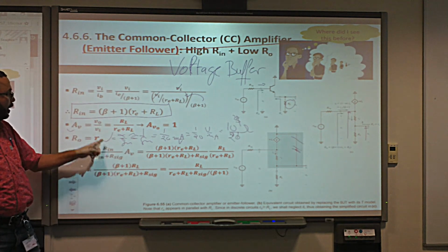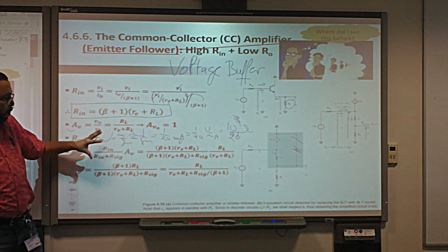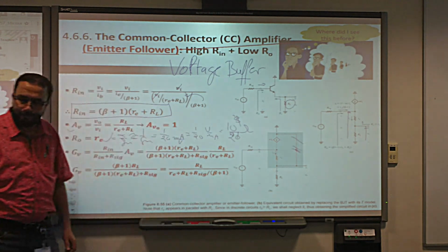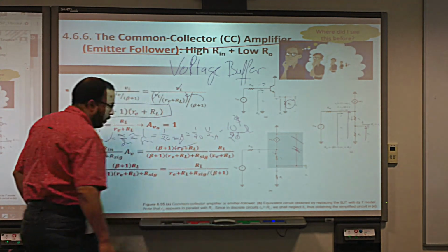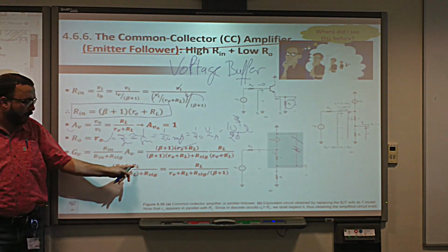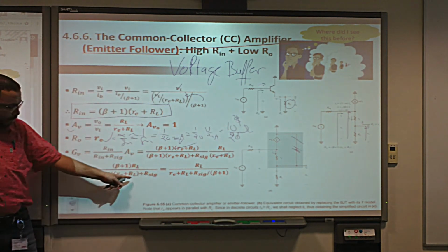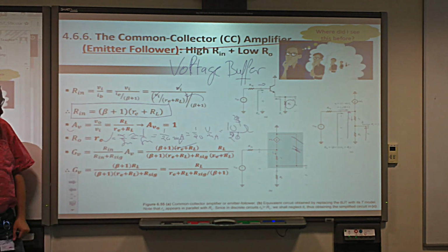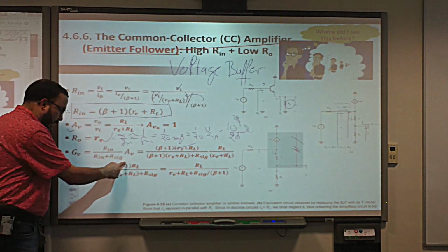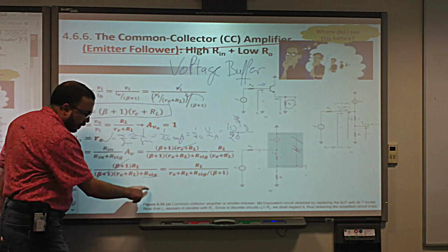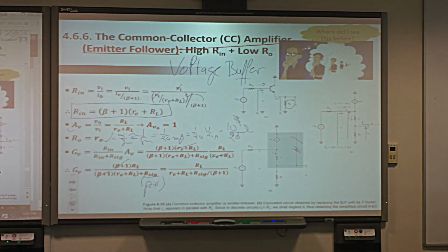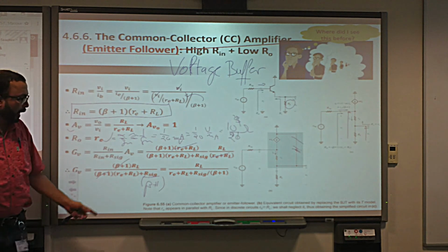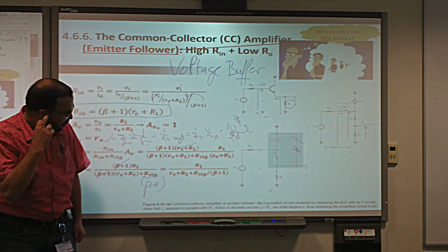And we have this, Rn is equal to what? The whole thing. Put everything together, you get this. You can see that you can cancel this with this. So the remaining will be beta plus 1 times Rn divided by all this. Now we can cancel with this one, but I have to get this one over beta plus 1, yes. Good. And we have this formula.